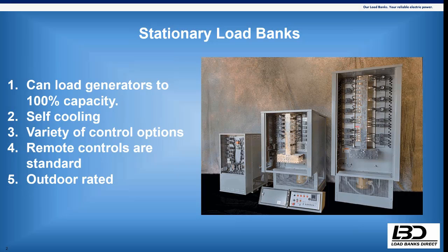So the outdoor unit is NEMA 3R to keep all the control components nice and dry and clean while it's installed outside. So those are some of the big points on the stationary load bank front. The biggest one, when you're comparing it, and we're going to get to the radiator mounts, is you're able to load to 100% capacity of your generator because they're self-cooled.